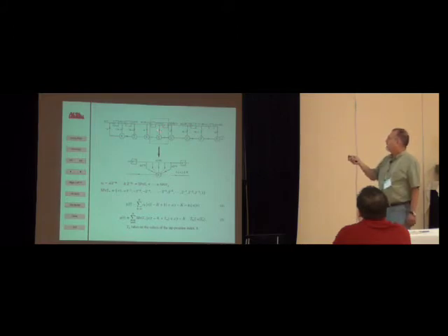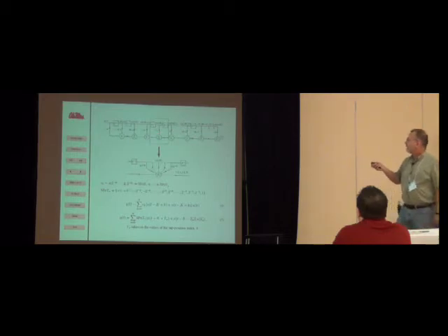to get around this, you can do something a little different to generate these coefficients, and I'm trying to illustrate this here. Whereas you can't multiply very quickly, it's very easy to take a binary number and divide by 2 or divide by 4 or divide by any power of 2. You just shift the binary point. And so